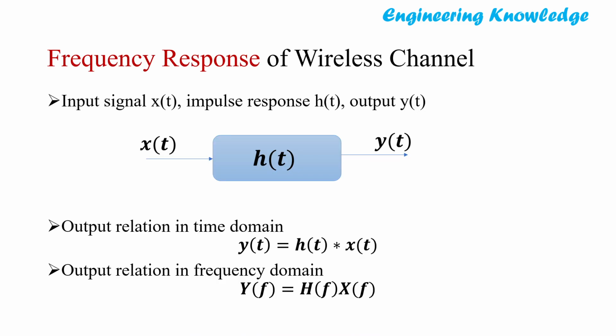Now we have defined the delay spread, which is the delay. Now delay is in the time domain. We also want to understand the frequency response of the system. So the delay spread will be related to the frequency response through the LTI system model that we have followed for the multipath wireless communication system.